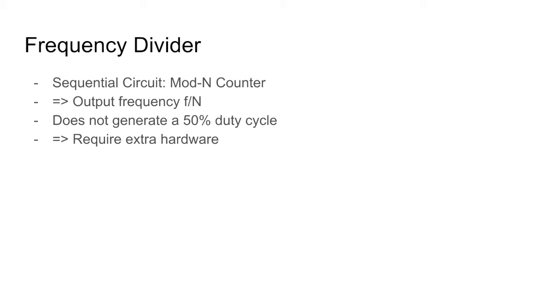Hey guys, so I'm gonna describe the method that we use for a frequency divider. Our frequency dividers or counters are formed by connecting flip-flops together, and any number of flip-flops can be cascaded together to form a divide by n binary counter, where n is the number of counter stages used, which is called the modulus. The modulus, or simply mod n counter, is the number of output states the counter goes through before returning itself back to zero, which means one complete cycle.